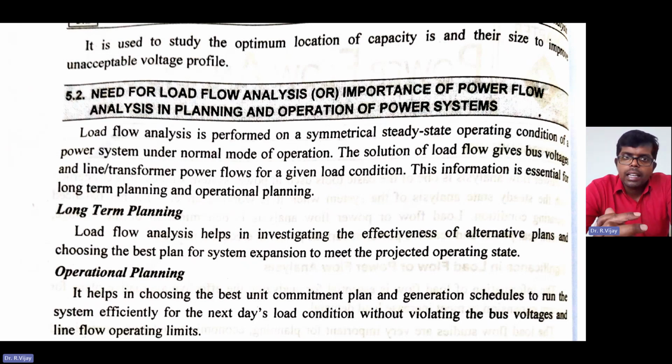Say, for example, one company is not maintaining the power factor constant. Definitely that will reflect in your nearby substation, whichever that particular industry is connected to. So what they will do, simply they will wait for 2 minutes. If not, they will just open that feeder.